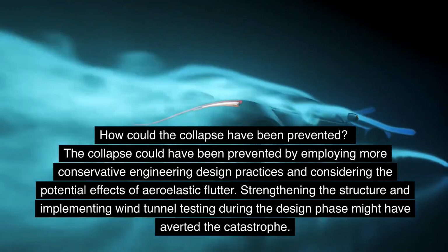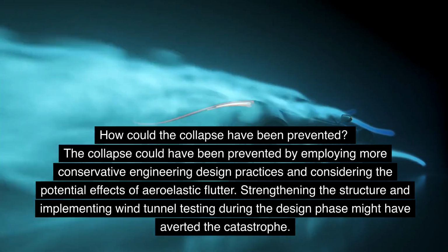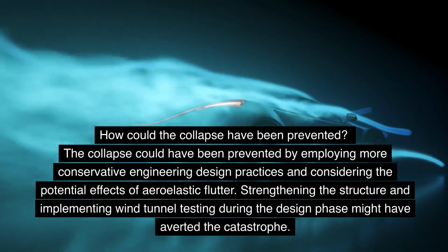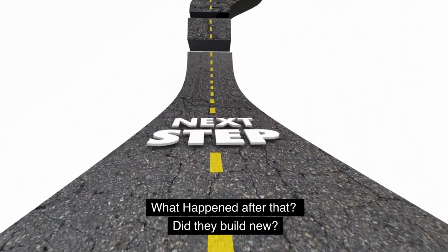How could the collapse have been prevented? The collapse could have been prevented by employing more conservative engineering design practices and considering the potential effects of aeroelastic flutter. Strengthening the structure and implementing wind tunnel testing during the design phase might have averted the catastrophe. What happened after that? Did they build new?